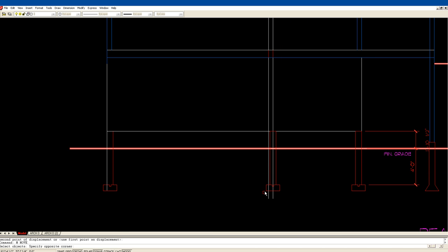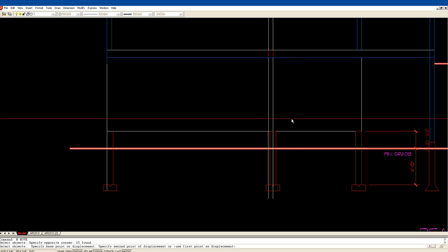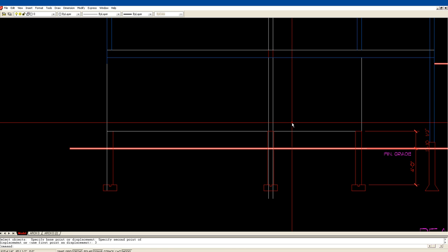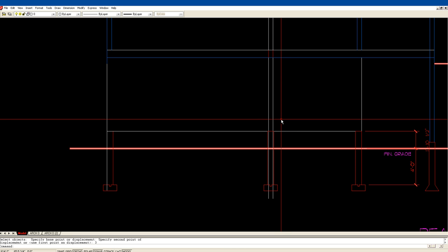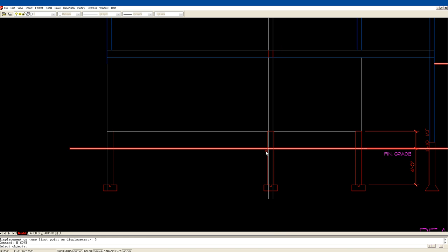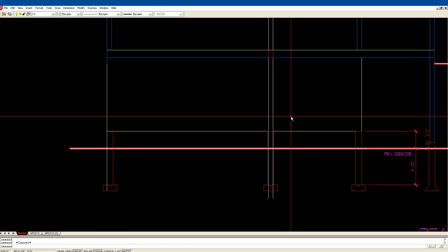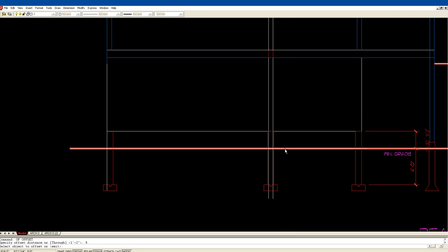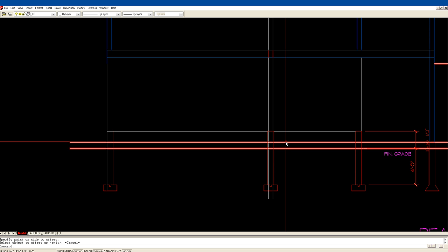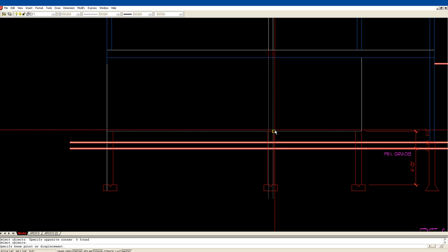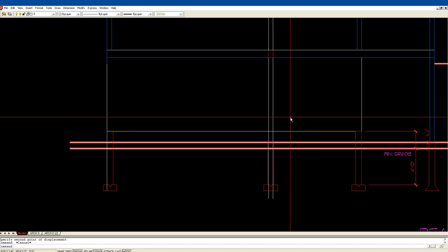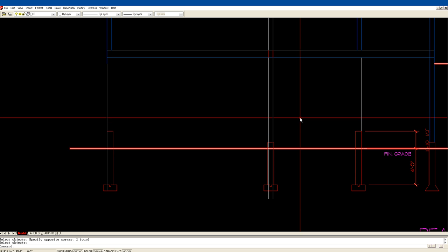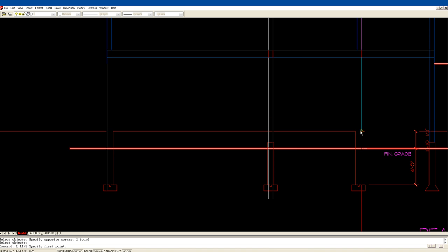And so I'm going to move, I'm just going to slide it, what, 3 inches? Yeah, that would get me to the center bolt, sure. There we go. And then I'm going to move it down because all this has to be is 8 inches out. So offset 8. And then stretch. I want to stretch just that red one down to there. Get rid of my construction lines. Actually, I could use that line.